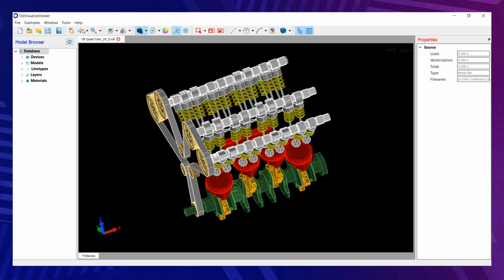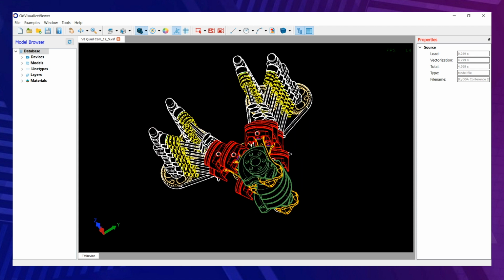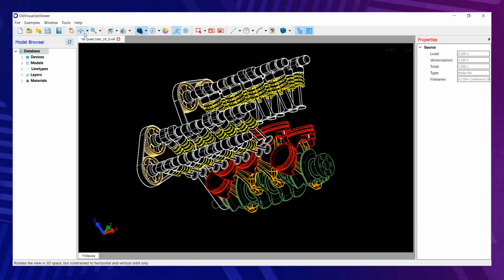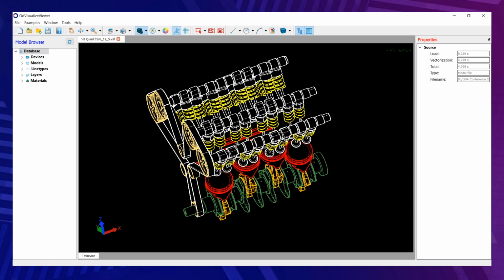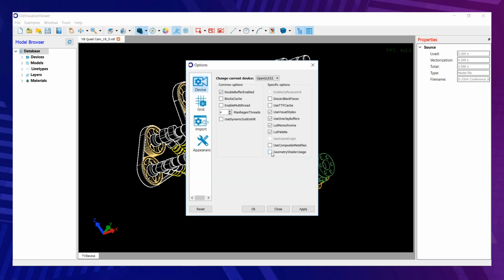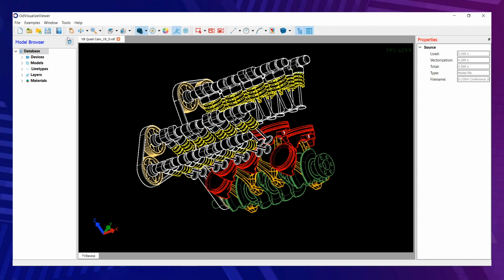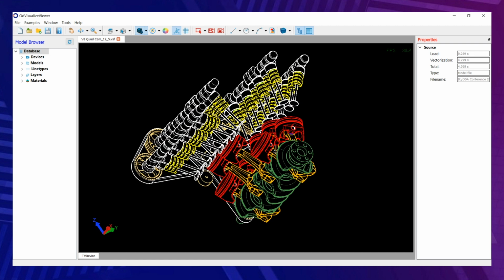On this demo, we will now switch on the hidden line visual style with silhouettes in the old mode, without using the geometry shaders. The main part of the calculations is on the CPU side, and you can see that we do not have good performance. It's only about 1.5 frames per second. Now we will switch on the use of geometry shaders, and there is no problem with performance. But here we should mention that only relatively new graphics cards support these geometry shaders well.